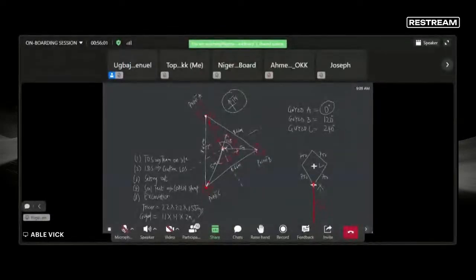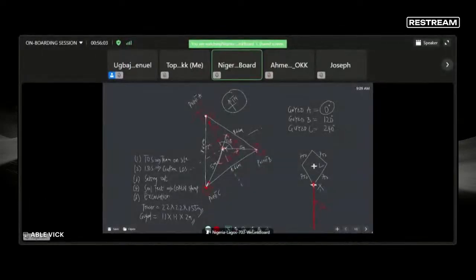Land is relatively flat. If it's not flat, it means you need to probably establish a benchmark and modify your excavation depth. If your ground is sloping like this, what is going to change is the depth; the width and the length will still remain the same. Understand?